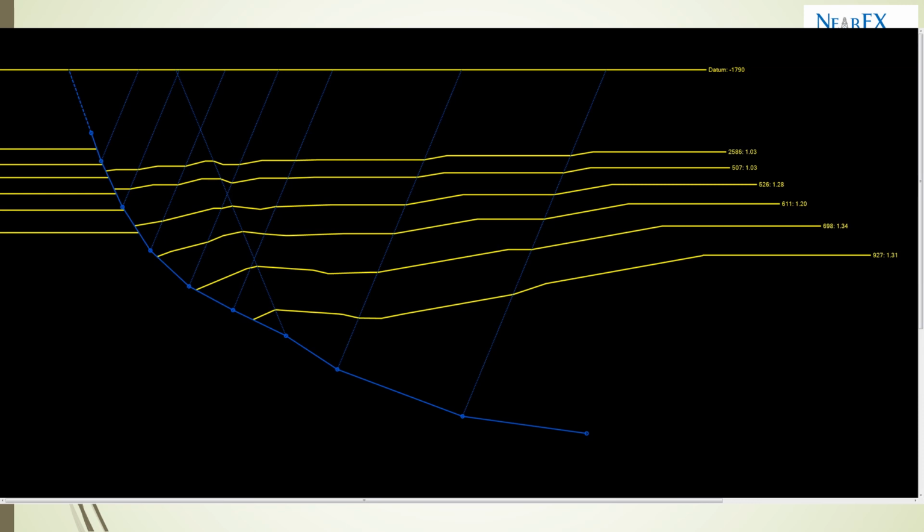With an interactive forward structural model, and here I'm using Structure Solver, you can modify points and put them where they may actually be as opposed to where you thought they were from the seismic. And the goal here is to modify the fault until you get a very, very good match with the overlying geology. And now you may think that's overkill, but there's a really important advantage in doing that.